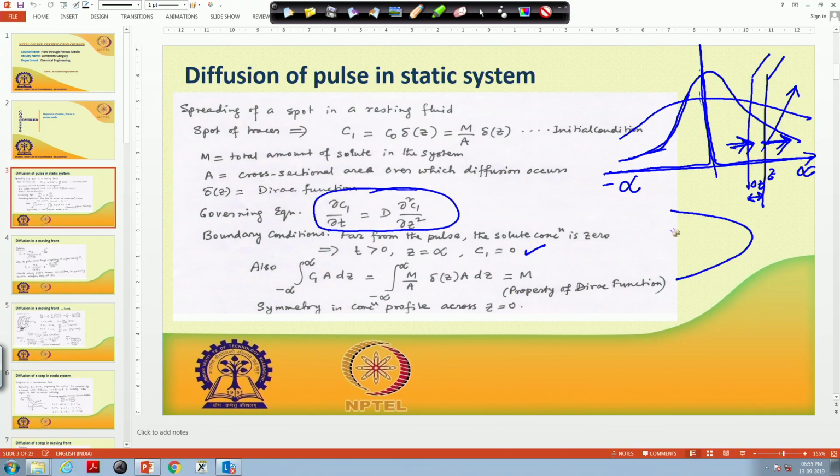Dispersion coefficient, if you are looking at dispersion in a capillary where you have a parabolic velocity profile, there we have already seen that when you have a parabolic velocity profile, then, suppose I have given a pulse, that pulse is now stretched in the form of a parabola. Had it been a plug flow, the pulse would have simply appeared as a straight line like this. So instead of that, this has been stretched in the form of a parabola.